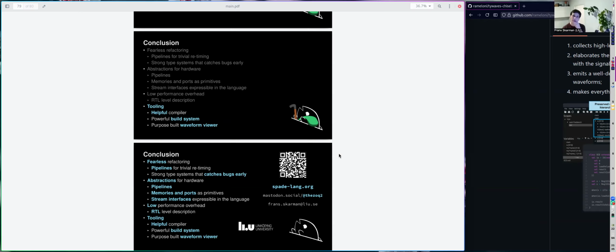There's no integration. The RAM example I was talking about, there I just added 20 registers at the end and let Vivado propagate them in. So you could do that. You could turn on retiming, put all your registers at the end, run the tool, see what the results are, change the registers. There's another HDL called Pipeline C, built by a friend of mine, that does iterative retiming, so you're not explicit about the location of the registers.